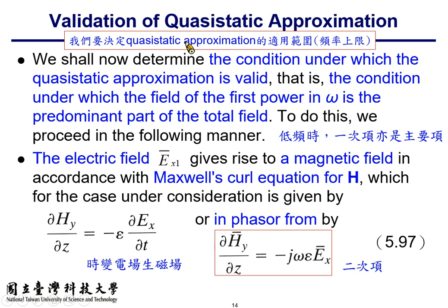So use the Ampere-Circuital law. The curl of H equals J plus the displacement current term, and here we don't have current in the structure, so we use this. So actually, you should have del Hy over del z minus del Hz over del y.